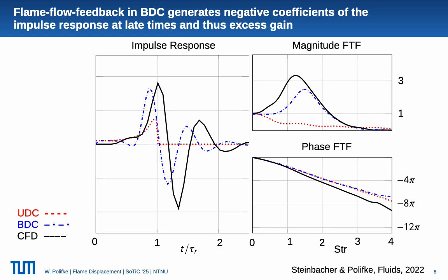However, the bidirectional model includes the effect of vorticity and the solenoidal field generating additional velocity contributions inside the flame cone. So the important contribution here would seem that convected velocity perturbations do not directly result from acoustic to hydrodynamic mode conversion, but they are generated by flame flow feedback, and they have a very pronounced impact on the flame dynamics, that is the flame heat release rate. And the question is, does the convective velocity model of the G equation as we know it misrepresent causality?